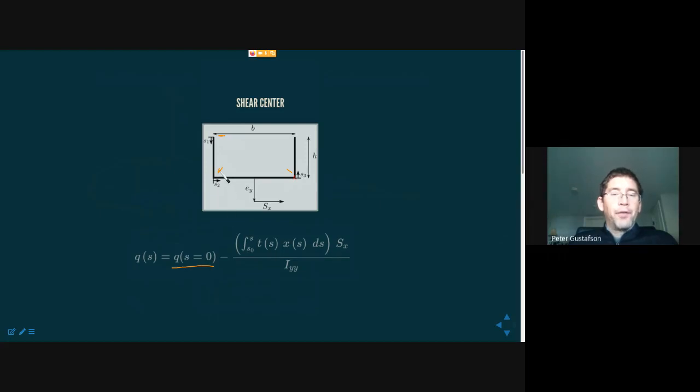So the value of the boundary condition here has to be the result of the calculation of the shear flow here, evaluated where S1 equals the total height. S1 goes from 0 to H down here. That's where we're identifying the boundary condition. It's continuity, really, between the two shear flow calculations.